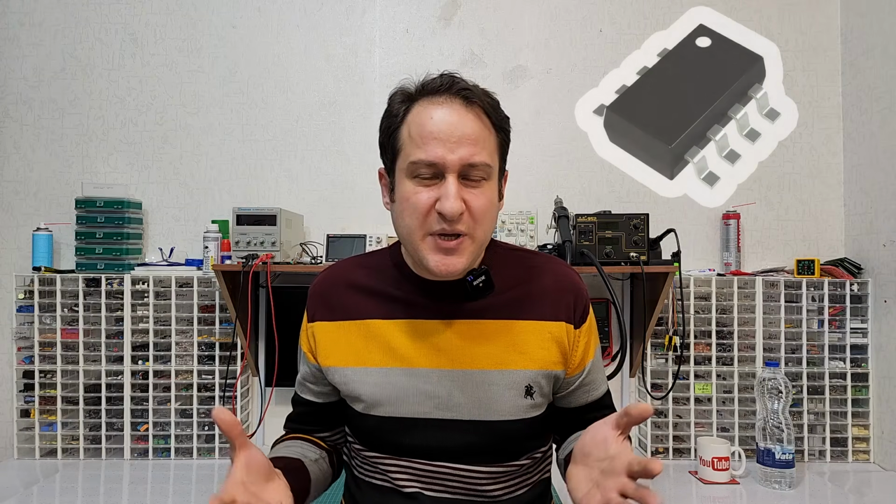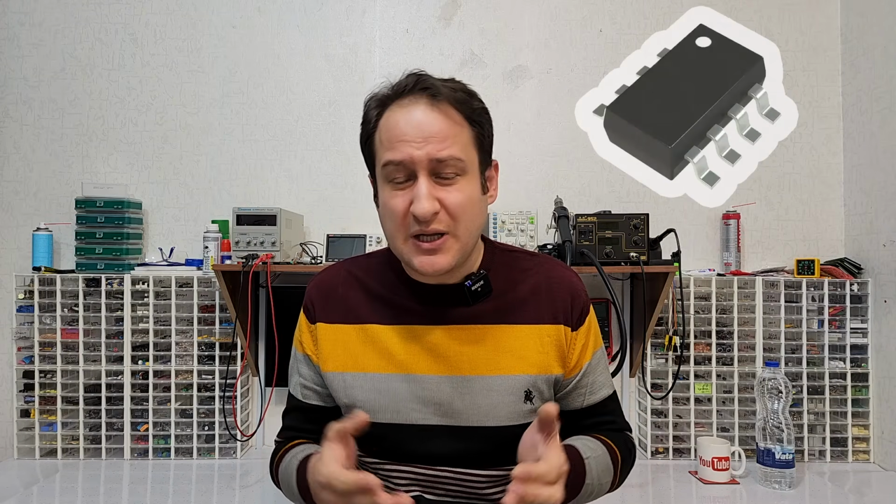Not all op-amp ICs can tolerate an input voltage equal to or close to the source voltage and work properly. For this purpose, there are special ICs like OPA2992 that should be used. But if you don't have access to these ICs, I can teach you a trick that will allow you to do the same thing with regular ICs like LM741 at the cost of slightly increasing measurement error.